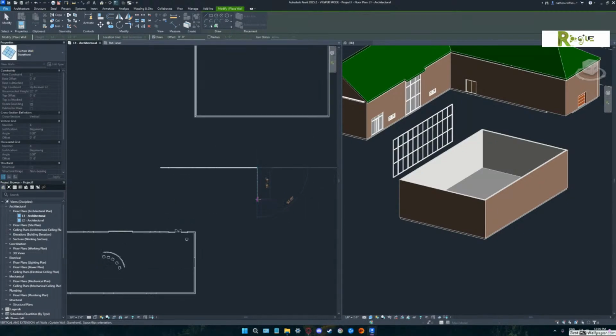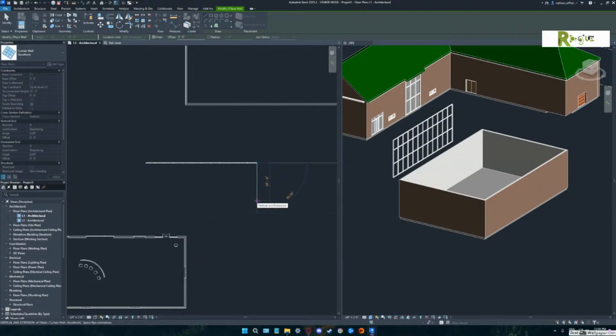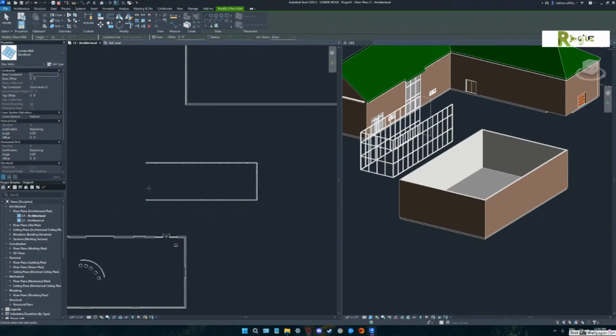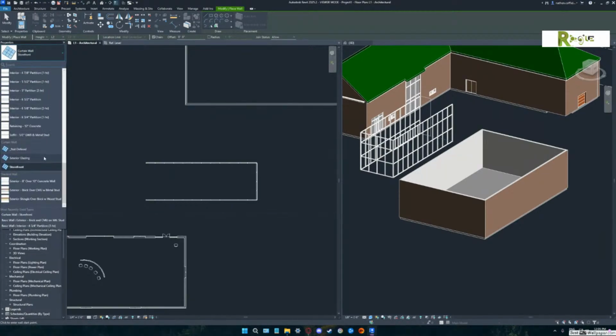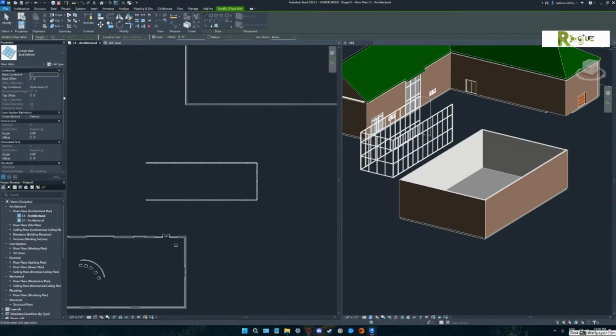And like I said, typically I don't get into this until someone's been using the software for a fair amount of time. Now, I would like you to try to draw the curtain wall that said something like undefined. You can finish that, and then go to properties. Hit escape one time. You're making a greenhouse is what you're making. Now go up to properties, and where it says curtain wall storefront, hit that and go down to the one that says not defined. Okay. Now try to draw yourself just a piece of curtain wall.